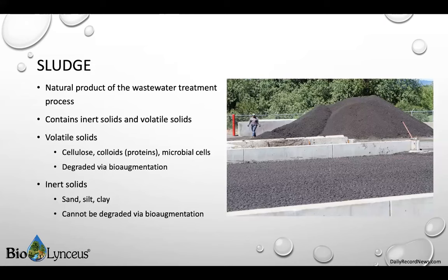Solids accumulation is unavoidable, so wastewater facilities are constantly looking for ways to efficiently handle these solids. Many facilities are turning to processing their sludge for secondary applications. The sludge is partially dewatered, most commonly by centrifuge or belt press, and then hauled to either farms for fertilization purposes or to landfills where it is used to cover domestic trash.